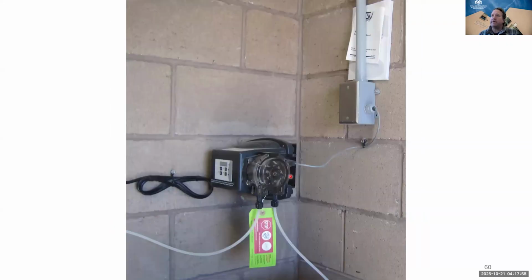Here is a peristaltic style chemical feed pump. This is a type of pump that's also used in medical applications, in dialysis, so that you do not have your body fluids in contact with a bunch of pump parts. Instead, we have a flexible tube inside of this roller assembly. As this roller goes around, it pinches that tube and pushes a little bit of chlorine through. This is our suction side, and this is our pressure side as it goes out to our water.